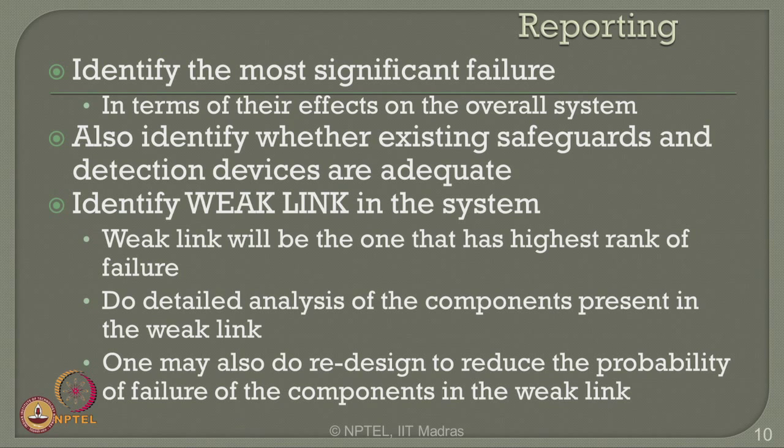So, this merit order arrangement will tell me which is the most vital or the critical component which has the most serious consequence of failure on the overall system. Therefore, we are trying to rank the failure in a specific order, preferably in a descending order. The highest component which has got the maximum consequence of failure will get the highest risk rank, as we also saw in Morgan's analysis. So, that would be the weakest link in a given mechanical system.